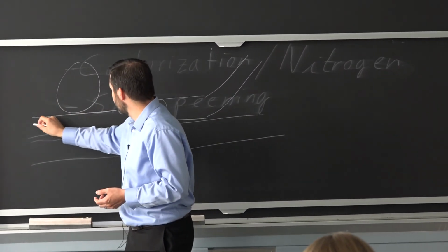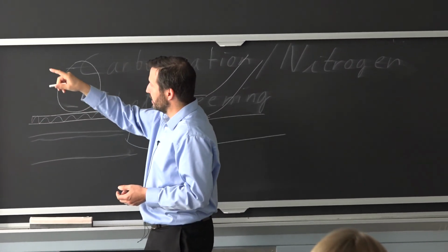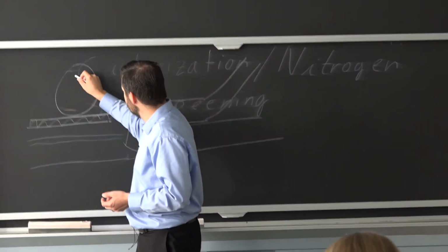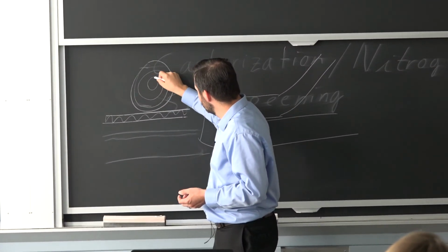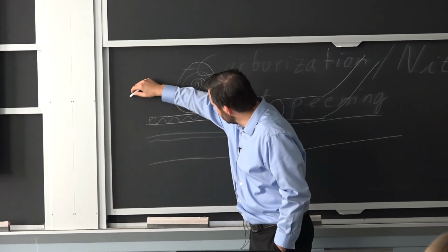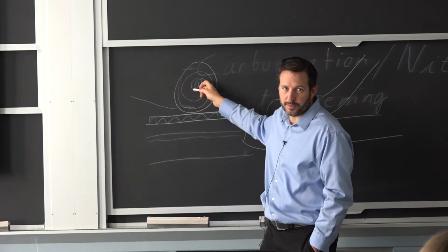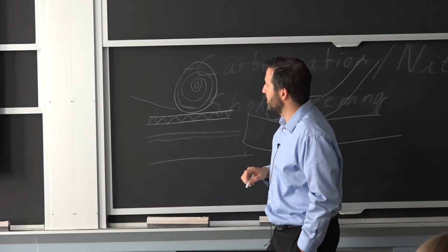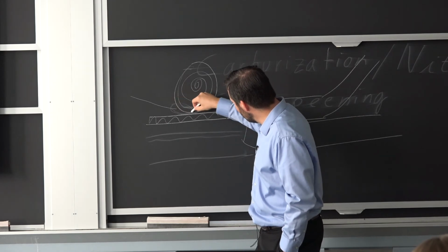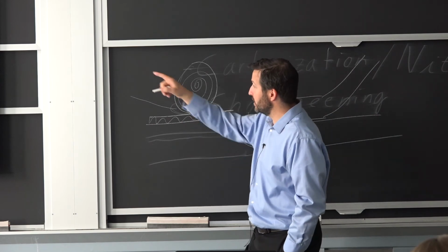So there are two things that happen. This material here, the flat piece, is thinner. It doesn't show there because we cut the bottom, but it's much thinner than this bigger piece. So what happens then is when you come with the heat, you need to heat a little bit more the thicker component. That's a necessity. And then the question is, are you going to be arcing only with a bigger component, or are you going to be arcing with both? And you see both cases.